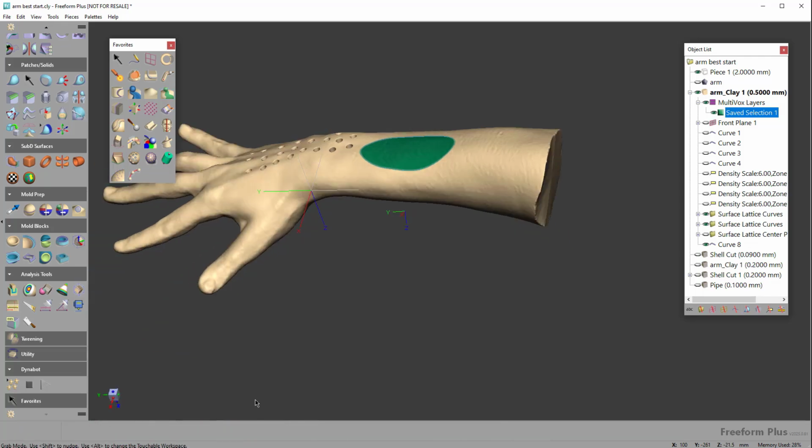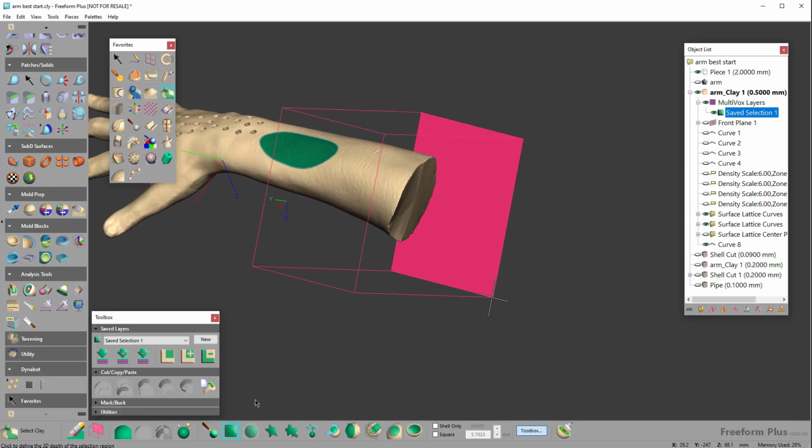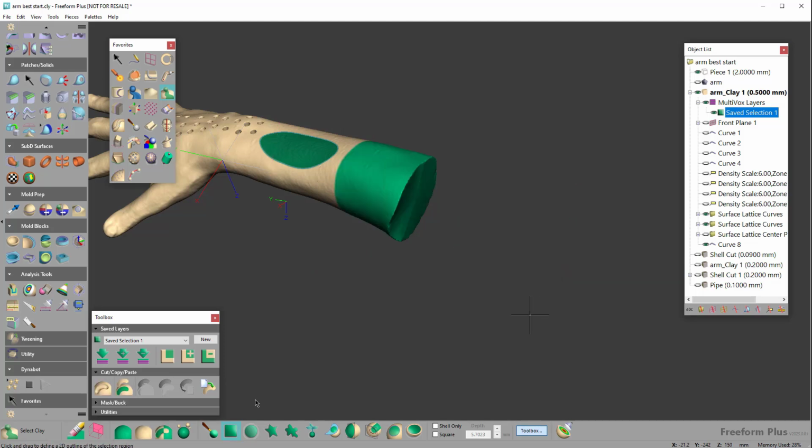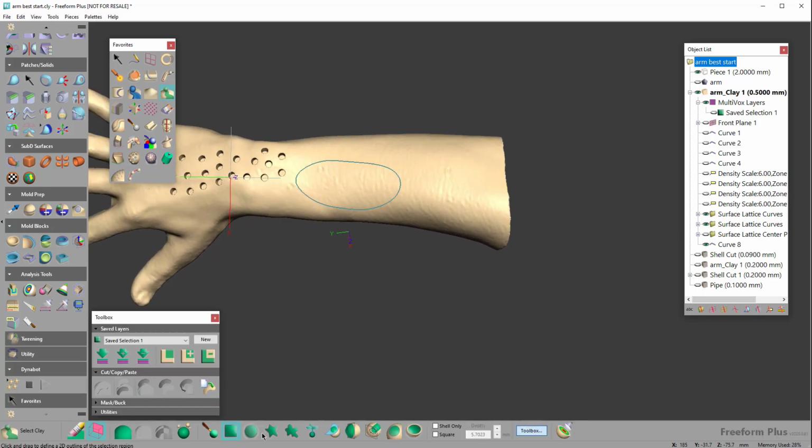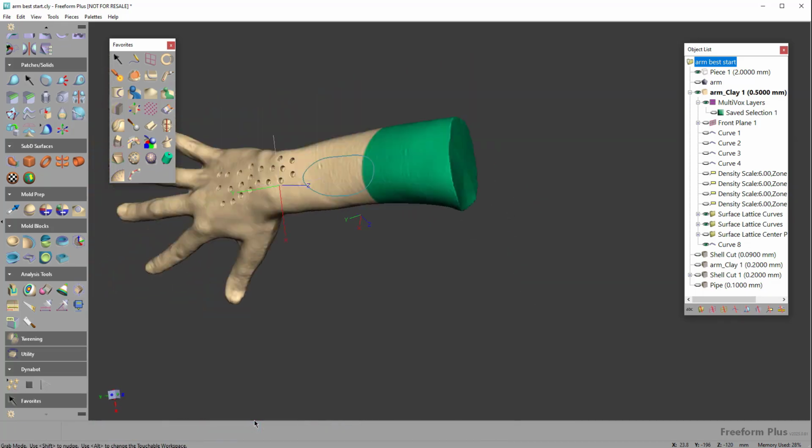Now in order to create a selection, I would have to rotate to the side and then move and then dictate how deep that selection goes through, which 90% of the time everybody wants to select through, right? So that is one of the things that we would do here, is give you the ability to turn on this 2D selection. So as I just window in, drag in, it selects all the way through automatically for you. And that is something that came out before that, it's just a thing that people forget that we even have. And it comes up because we added the circle select now, right? And it works alongside of that here.